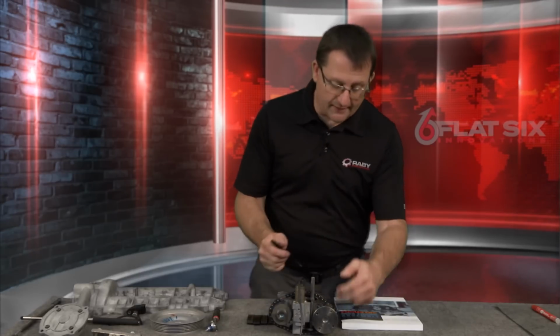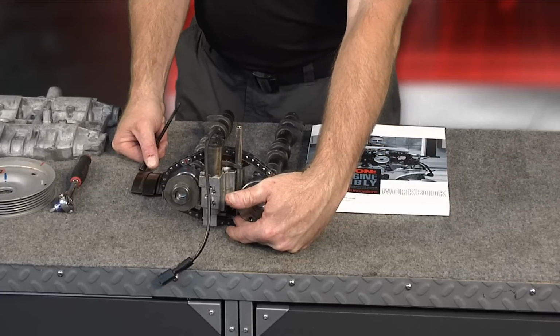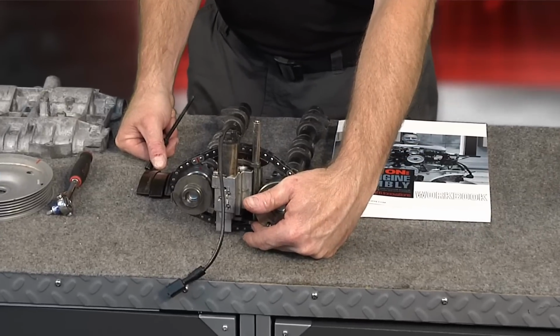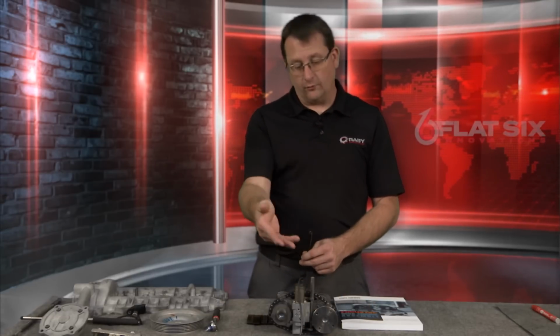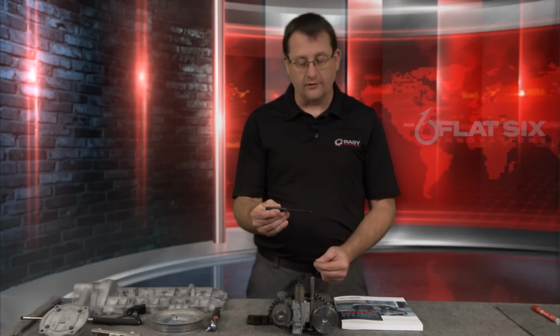You can look at the threads in the lowermost portion of the chain adjuster unit and see if they are right-hand or left-hand threads, okay? If they're right-hand threads, you have a pretty good opportunity to make your own one of these from whatever you can find locally. If it's left-hand thread, like the black one here, it's going to be kind of hard to find left-hand thread stock, even though I've been able to buy it at McMaster-Carr, Grainger, some places like that, take a couple of nuts and make one of these. At the end of the day, it's a cheap tool that you can buy from BAUM along with the rest of your tools.